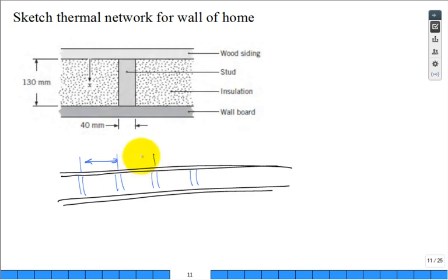They like to have it nicely spaced, and often they're on 16-inch centers for studs. Okay, the 2x4 studs. And if you're up north, they won't have 2x4. They'll have 2x6 studs for thicker walls, more insulation, and that's not common down here at all. And they'll even have steel studs instead of wood studs.